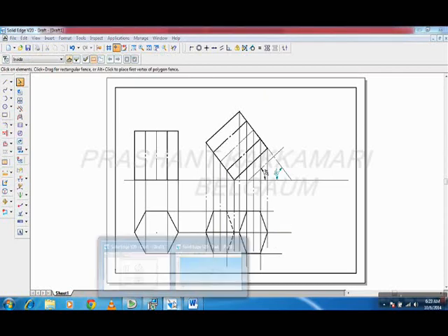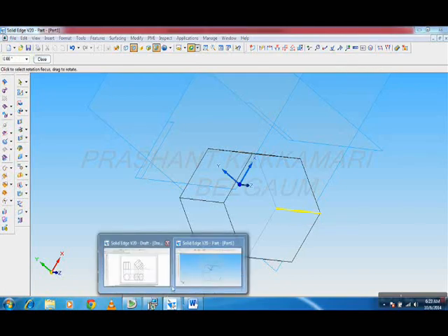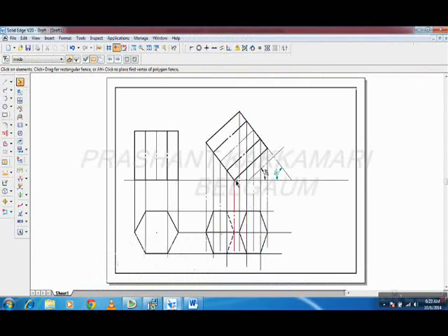Now come to other edges. Are any other edges invisible? Okay, this is invisible. What is this line? It is joining from A to this G, what I have taken. Now see, this A and this G is coming below this edge, and it is invisible to the observer who is observing from the top. So that's why I will draw one line of thickness.